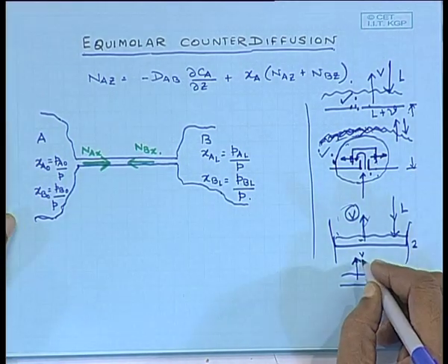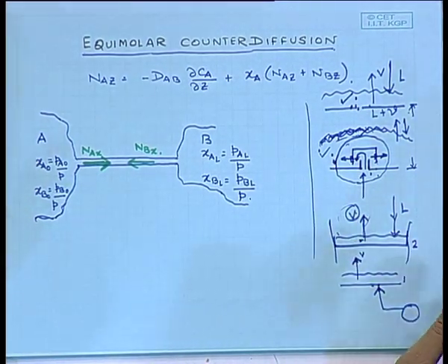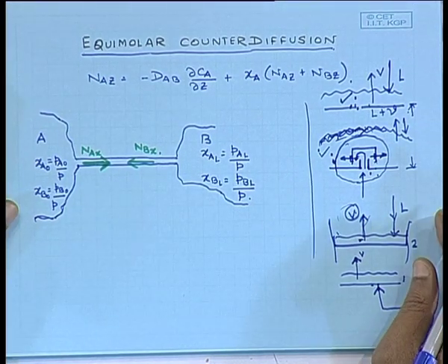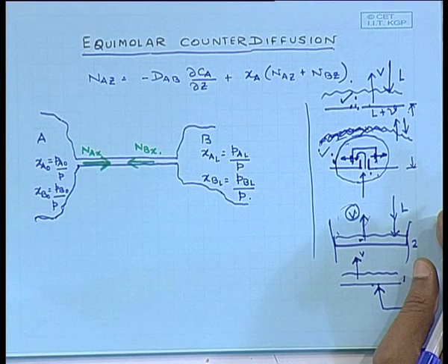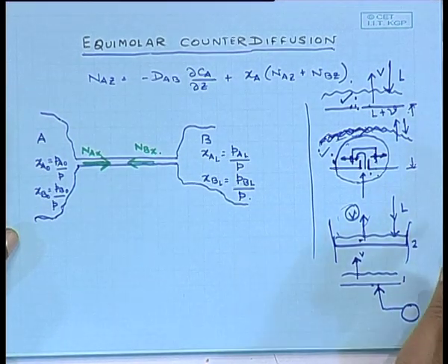So, 1 mole of vapor coming and condensing here, generating some amount of vapor. Will it be 1 mole? Same or different? Same, sir. Why same? Steady state. Otherwise, there will be accumulation. Let me think of it from an energy point of view.